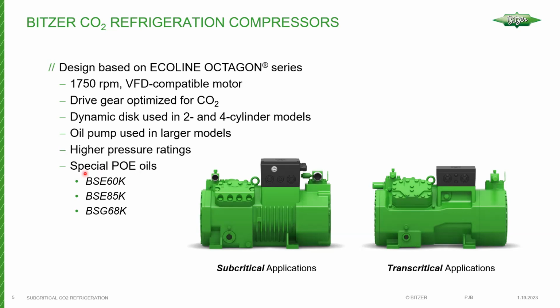So basically, these oils that you see here are higher viscosity. We have one oil, which is considered the standard oil, for subcritical compressors, say in a cascade circuit where the condensing temperature is also subcritical. I know, whatever that means, right? We'll get to that shortly.